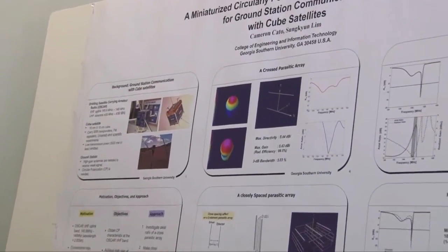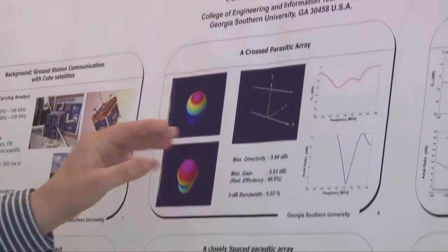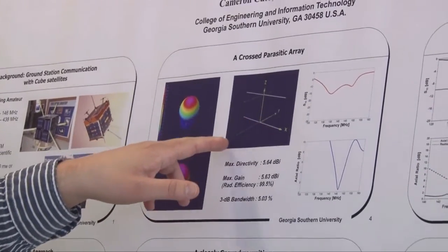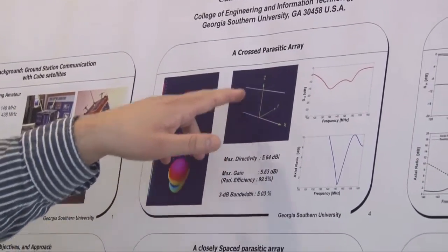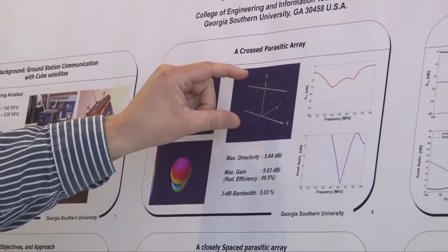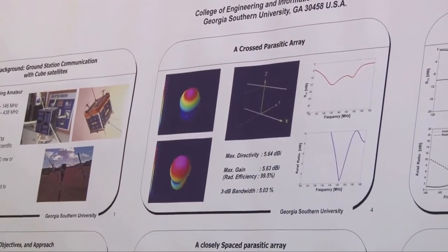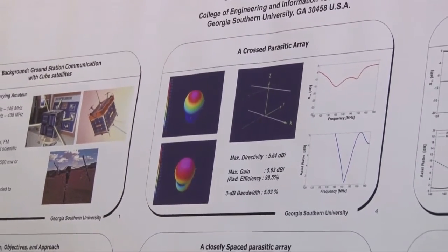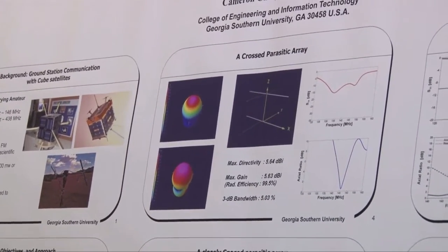From here, I wanted to miniaturize the antenna. Part of that is reducing the overall width of the driver and director, and also bringing the driver and director closer together in spacing. As we bring the director and driver closer together, the radiation resistance of the antenna tends to drop. An antenna needs about 50 ohms radiation resistance normally to match with the common coaxial cable that you would see, for instance, in your home theater system. Otherwise, power will not be transferred efficiently.